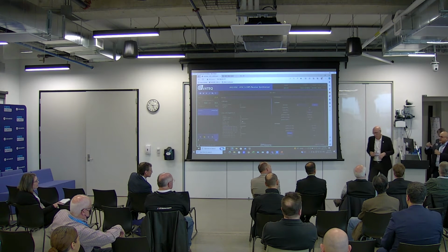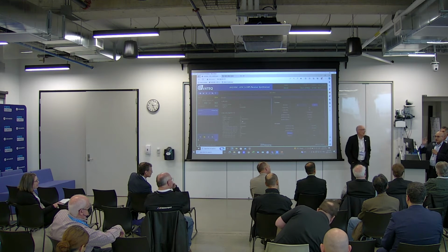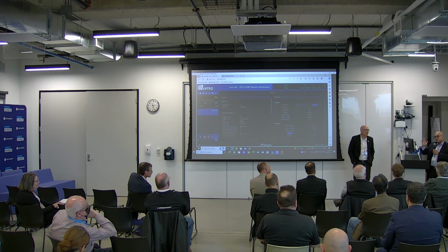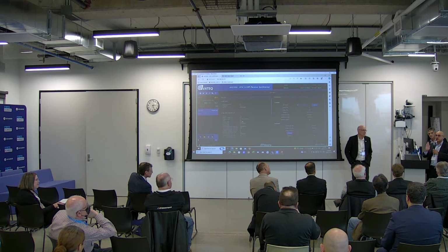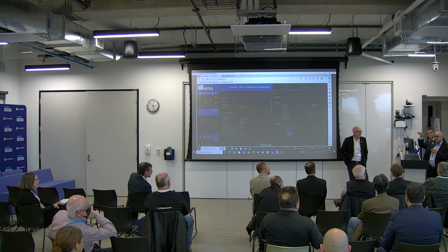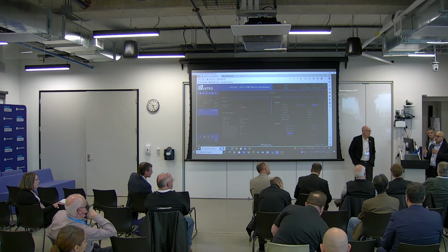I'd just like to add that we plan to receive many towers, but remember that we're expecting line of sight, but sometimes we may have multipath. So the quality of time from all the towers will not be the same. It will vary depending on the distance and on the multipath. So we have the flexibility of mounting as many as needed, possibly pointing to the leader towers, because there's a cost associated with how many followers you want.